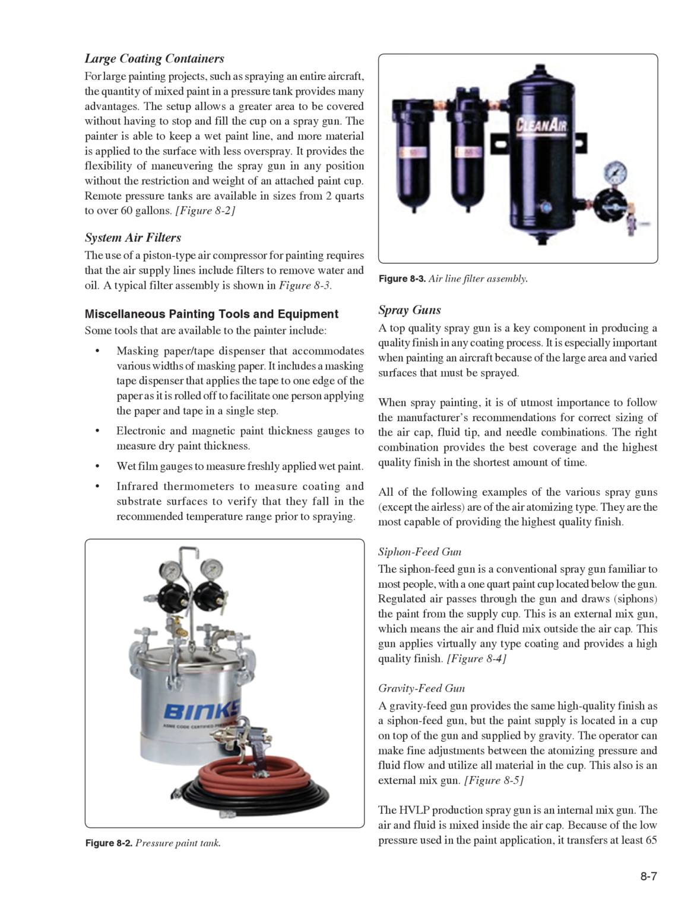All of the following examples of the various spray guns, except the airless, are of the air atomizing type. They are the most capable of providing the highest quality finish. Siphon feed gun. The siphon feed gun is a conventional spray gun familiar to most people, with a 1-quart paint cup located below the gun. Regulated air passes through the gun and siphons the paint from the supply cup. This is an external mix gun, which means the air and fluid mix outside the air cap. This gun applies virtually any type of coating and provides a high-quality finish.